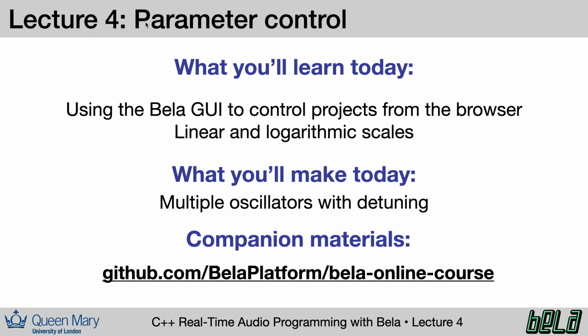So over the course of this lecture, you will learn how to use Bela's browser-based GUI as a way of controlling the projects that are running on your Bela board. We're also going to look at linear and logarithmic ranges for parameters and how to rescale them. In the course of this lecture, you'll make an audio generator that has multiple oscillators slightly detuned from one another, which is a common technique in modular synthesis to produce a richer sound.